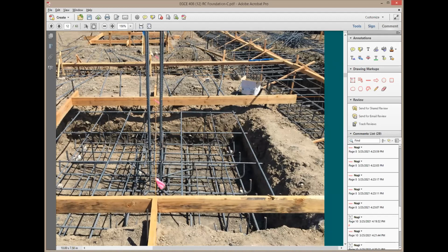Yeah, I always wondered, does having the spacers provide a place where water could potentially seep through later on or into the concrete and then corrode the rebar? You mean from the side? In the bottom, because you know how in the bottom they have those little gray spacers to provide the clear cover on the bottom of the footing? Yeah, these blocks, right? Yeah, I always wonder, is that a potential place where water could go through? This is why we have plastic, but here they are made out of cement, so it's going to be the same as the material of construction. So sometimes you do plastic, sometimes you do cement, so they blend in with the cement. Got it. Thank you.